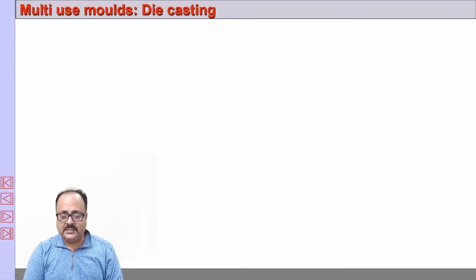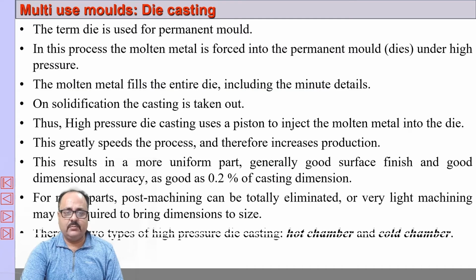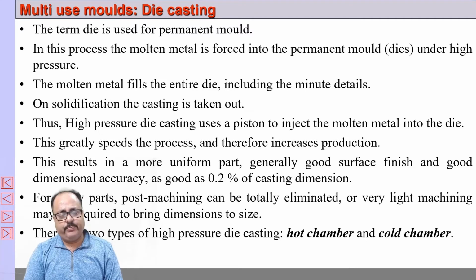In this lecture we will be discussing die casting, centrifugal casting and continuous casting process. So die casting is basically a casting process where you use a die or permanent mold, and in this die we fill the die cavity with molten metal under pressure. So it is called pressure die casting actually. And it can be of two types, hot chamber die casting and cold chamber die casting.